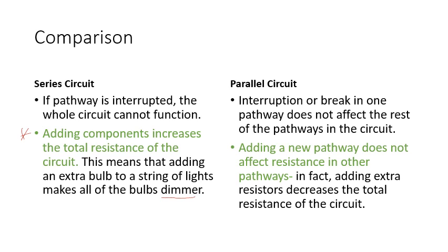Now I'm going to show you one thing that you do need to know and one thing you don't need to know for our purposes, but you will need to know this again in high school, I do believe. If I were to give you a circuit and I wanted you to find the voltage and I give you the current and a series of resistors, you'd have to calculate the total resistance to plug back into the Ohm's law equation to find the voltage. In a series circuit, the total resistance, R is for resistance, T is for total, is equal to the resistance of one resistor plus the resistance of the other resistor plus however many resistors you have. So there's a series right there.